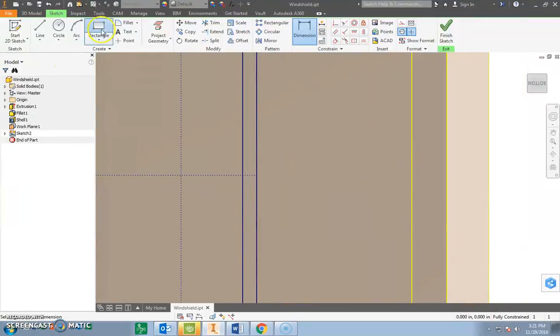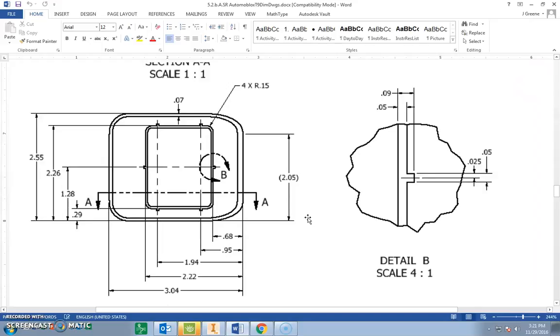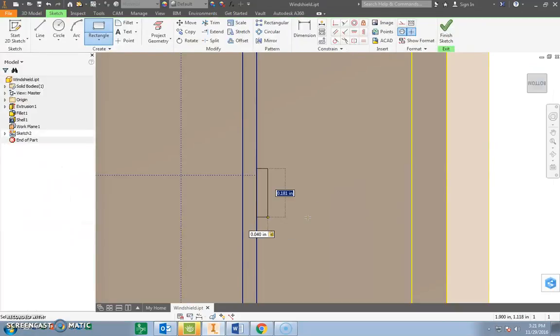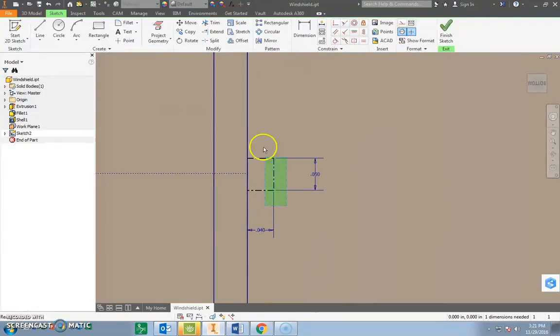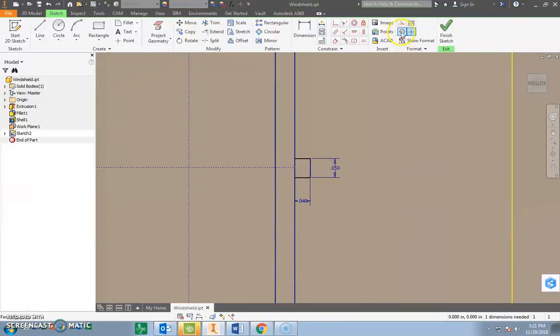So I'm going to start here. I'm going to grab a rectangle, click on this object, and just type it in. It comes off 0.04, and it is 0.05 in depth. So I'm going to place that there. If you did turn on center lines, make sure that's turned off for every other subsequent one, or it's going to get a little freaky.